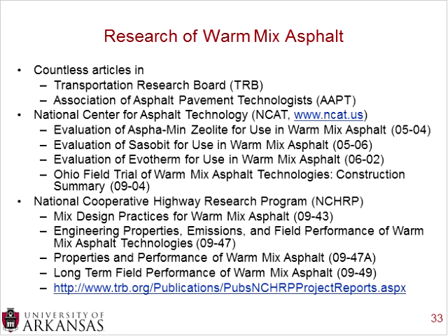Now, I realize that working at a university, I may have access to reports like this that not everyone has. So I also found some reports that are online, and they're available free of charge. One excellent source is the National Center for Asphalt Technology, or NCAT, and their website is simply ncat.us. They did 3 different evaluations. One was on Aspha-min zeolite, which is a foaming process. One was for Sasobit, which is a wax process, and one was for Evotherm, which is a chemical process.